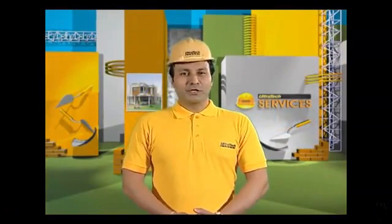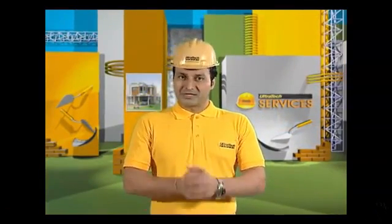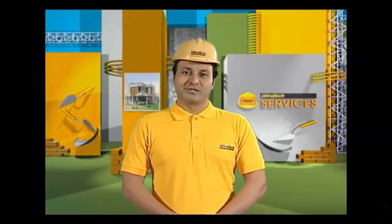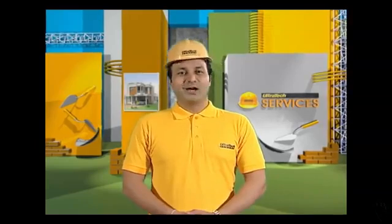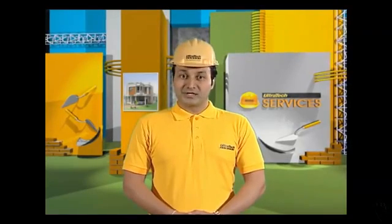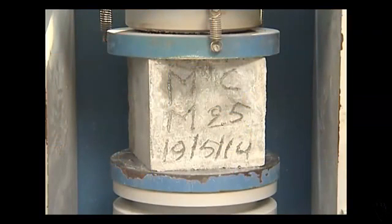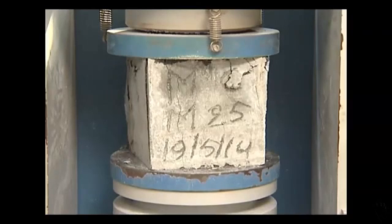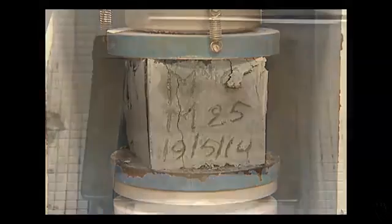Compressive strength is one of the critical properties of concrete to be tested, as it is linked with load-carrying capacity and durability. Come, let's see how the cubes for compressive strength test are cast. Oh yeah! This is a simple test consisting of cast cubes of concrete tested on a compression testing machine after the concrete hardens. Most of the desirable properties of concrete are qualitatively related to its compressive strength.